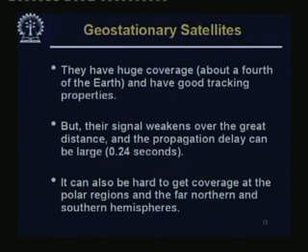So, they have huge coverage, as I mentioned, about a fourth of the earth, and have good tracking properties. That means you can track it very easily, but their signal weakens over great distance and the propagation delay can be large. So, you see the propagation delay we are talking about is of the order of 0.24 seconds. Okay. Usually we talk in terms of milliseconds, but here we are forced to talk in terms of seconds, which is not a very good thing.